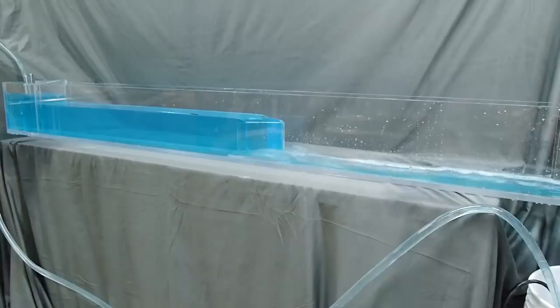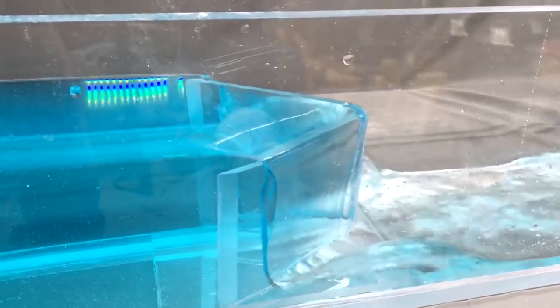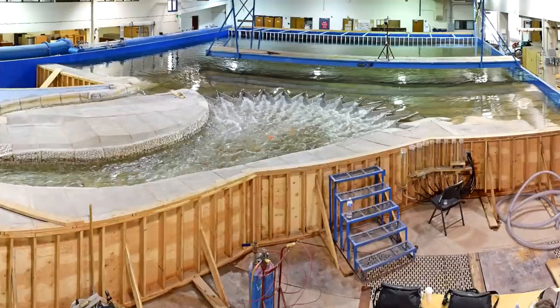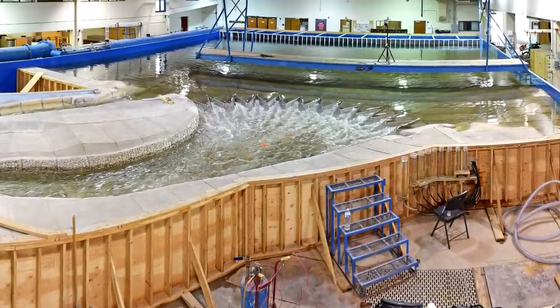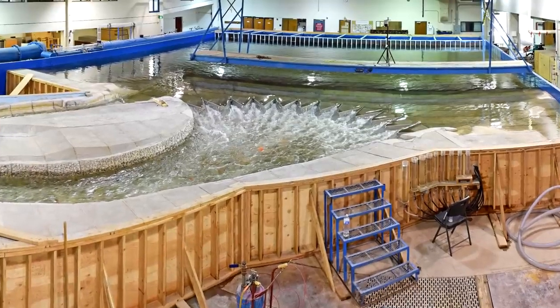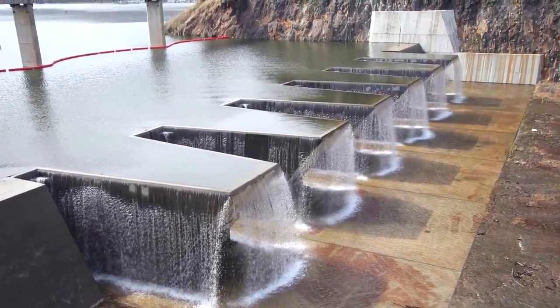You can see that even though the weir is passing the same amount of flow, the water level upstream is lower, almost half the distance to the crest from the original level. We flatten the rating curve, allowing for greater discharge at a lower water level. Nonlinear weirs with folded cycles like this are called labyrinth weirs, and they're becoming more common as hydraulic control structures. There are also rectangular versions called piano key weirs.